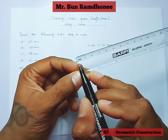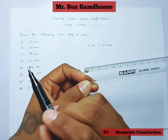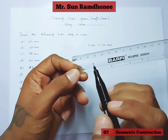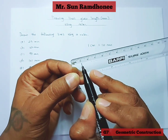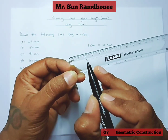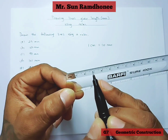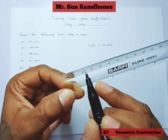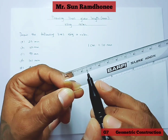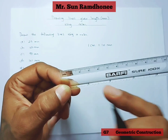For example, if we have 27 millimeters, it would mean that we have 0, 10 millimeters, 20 millimeters, and then we have to count these small divisions. So in this case, it will be 20, 21, 22, 23, 24, 25, 26 and 27.